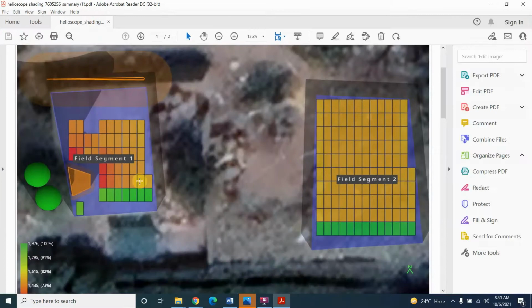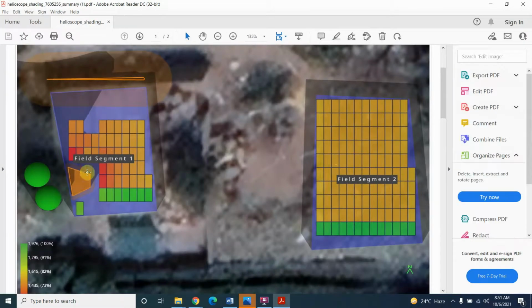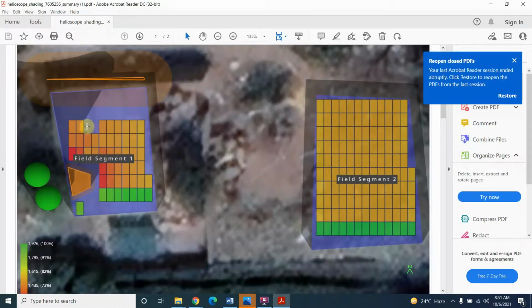You can see here the report. For example, I have decided on two locations, and due to the shading area, some solar panels are skipped, because of one hurdle and two trees. Due to the shading of these trees and this hurdle, some solar panels you can see here are skipped, and also there is a 3 meter spacing from this line where no solar panel is installed.